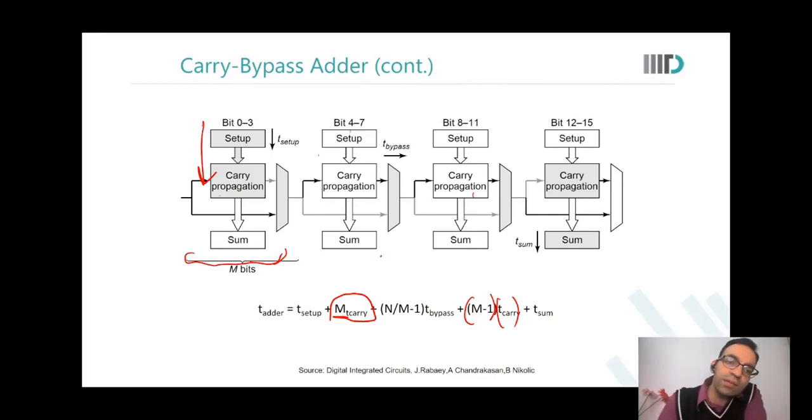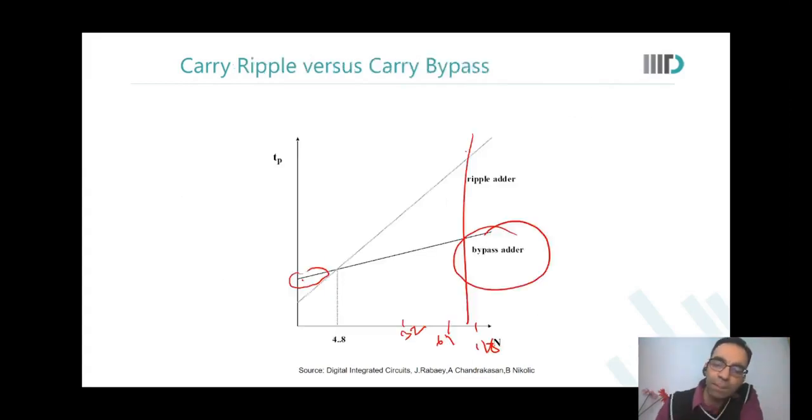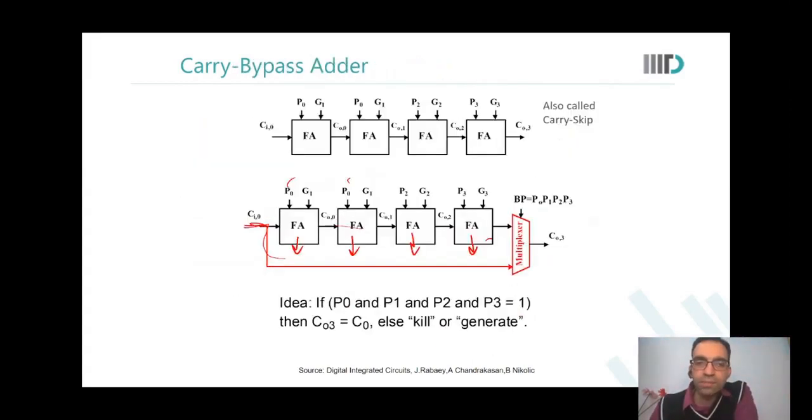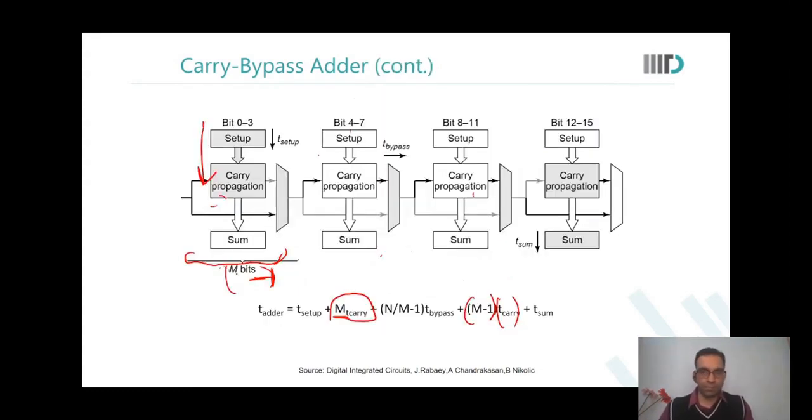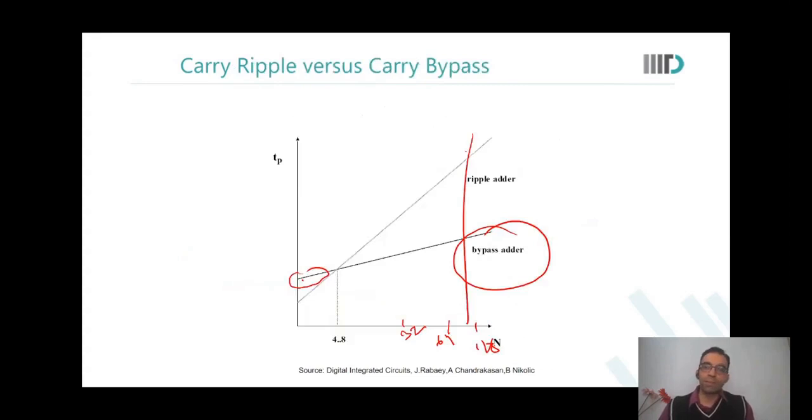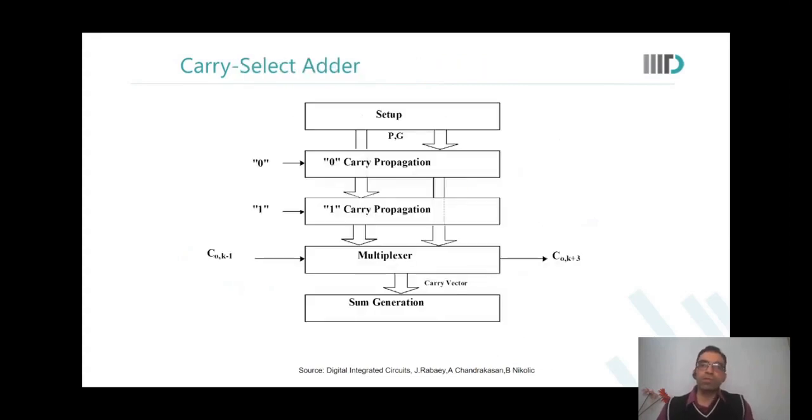And for this one in itself, if there are M bits, then that would mean M minus 1 times ripple could happen at least in this one, is it not? Even for a 4-bit thing, if the carry has to be generated like this, there will be 3 ripples happening inside it, is it not? Yes. That is why. Okay, sir. So, is it clear till there?